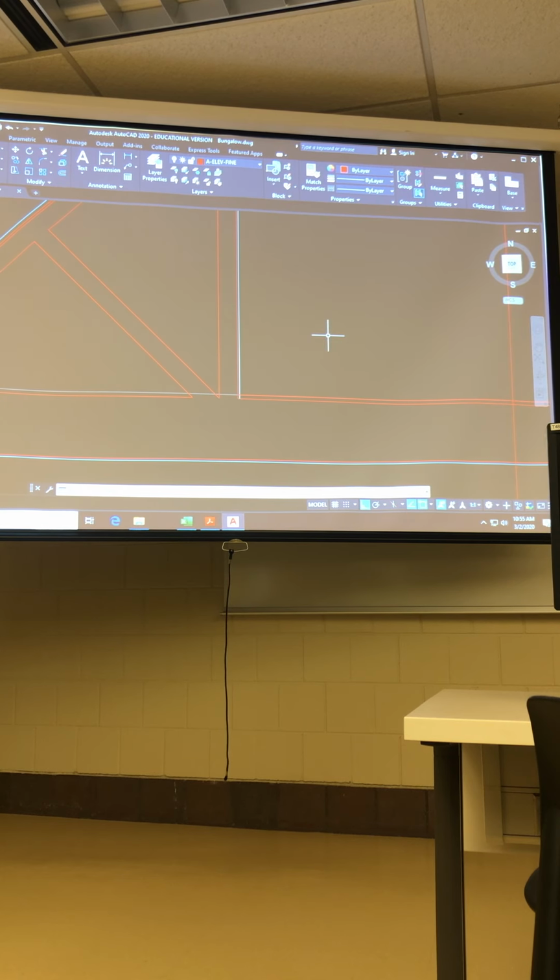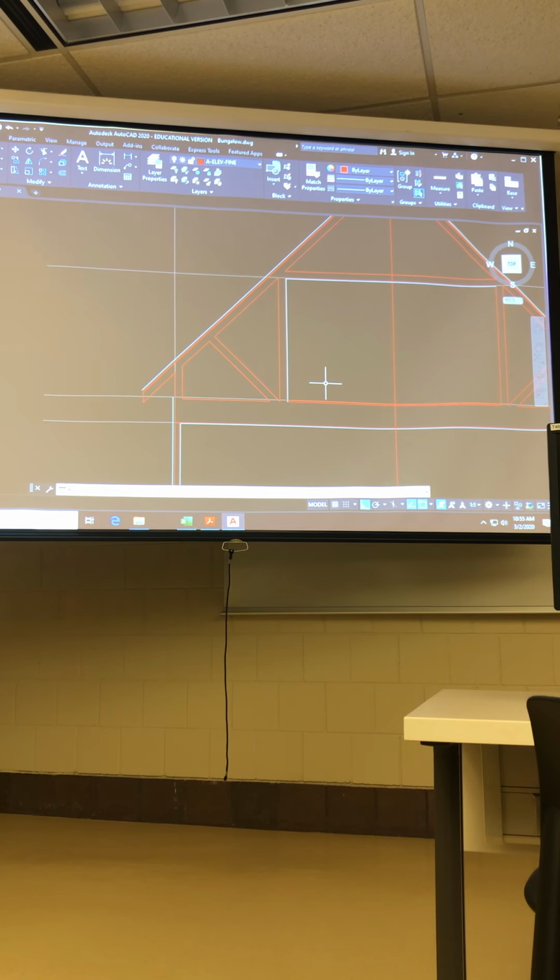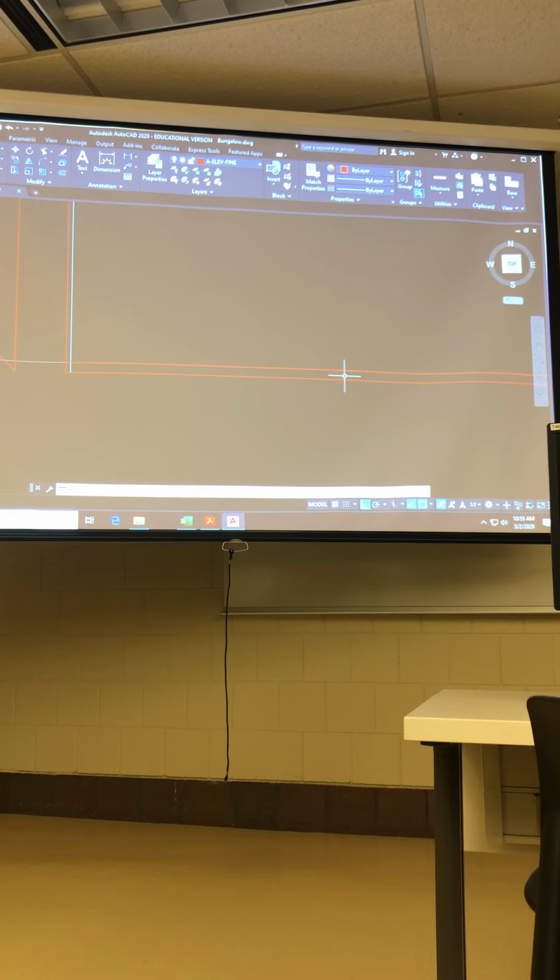5/8 on the ceiling. 5/8 on the seam. Yep, exactly. We're almost done. Again, this is our structural floor sheathing that we have on top of our bottom chord of the truss, that 1 1/8 inch thickness. We have a thickness for our finished floor on top of that. And I'm just going to assume that our finished floor material is 3/4 of an inch in thickness.